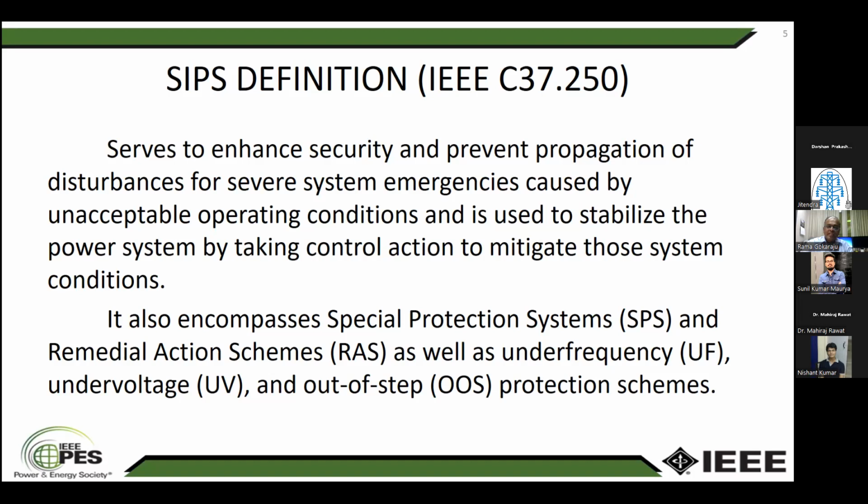For controlled islanding, the intelligent islanding that I'm doing. So out of step tripping, that is the synchronous generators, right? Or the loads, the synchronous motors. If they start slipping poles, we have to bring them offline. And we have to do it as quickly as possible. If we can predict it, it is good. And if there are some generator trips, we want to do islanding on the system.